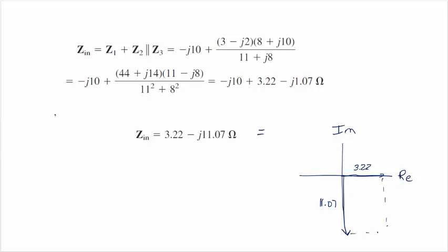And so you can get a total impedance Z right here, and Z will equal, by Pythagorean theorem, the square root of the real part squared, the resistive part, the 3.22, it's a right angle, plus the imaginary part, the X part, whether it's C or L, squared.